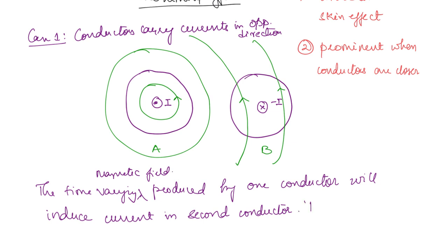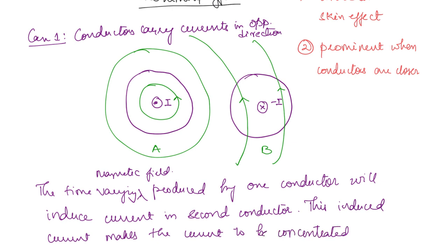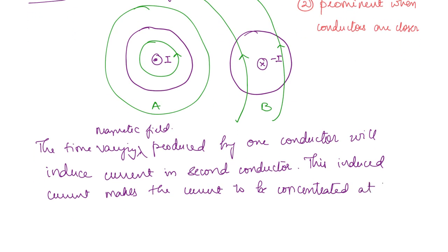And this induced current is going to make the current to be concentrated at the regions which are nearer to the adjacent conductor.